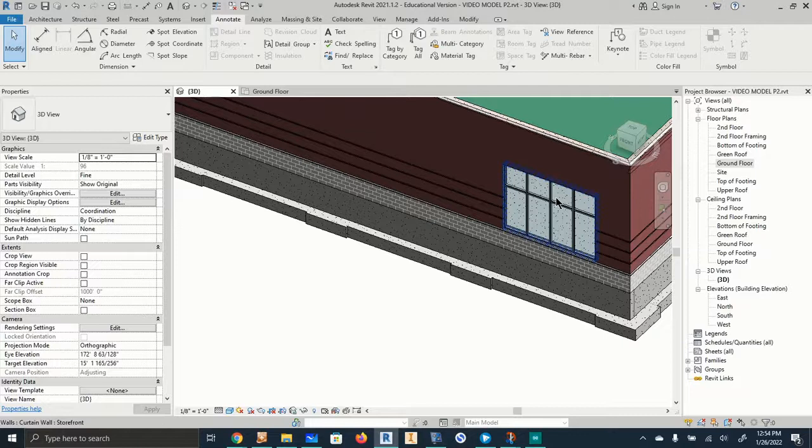You can also do these on the interior, okay? So you could put a wall in and a partition wall and then drop a curtain wall in it, so you would have like big glass windows in your room. Again, make sure that your curtain wall terminates before the top of your wall you're putting in it.